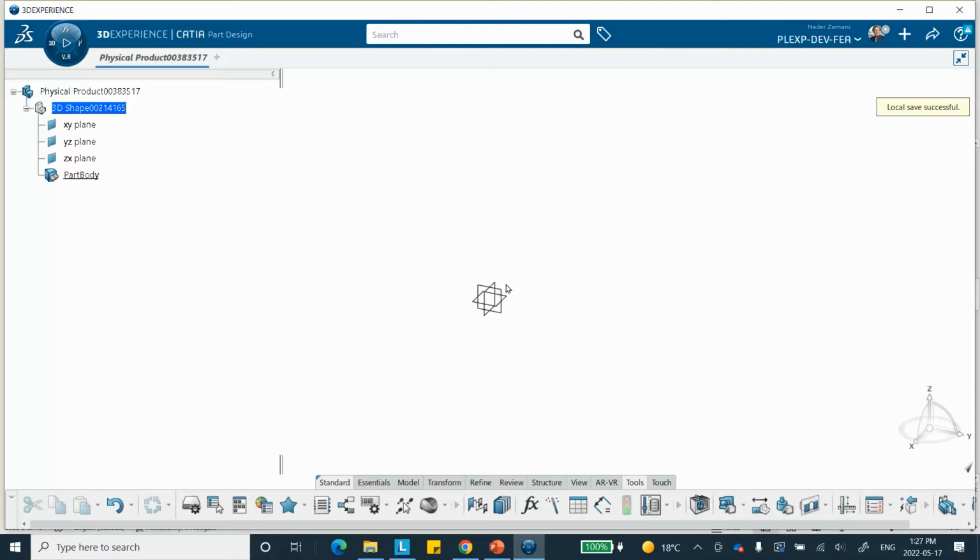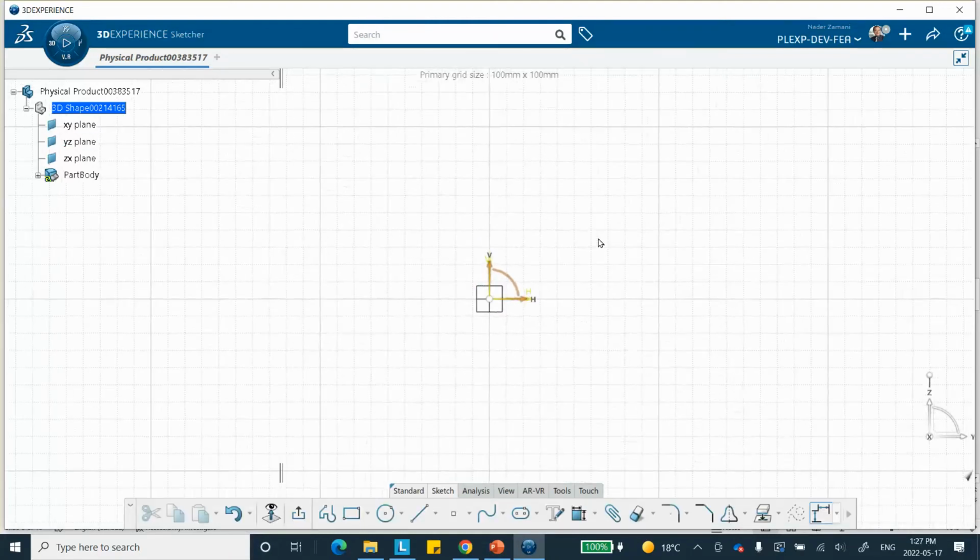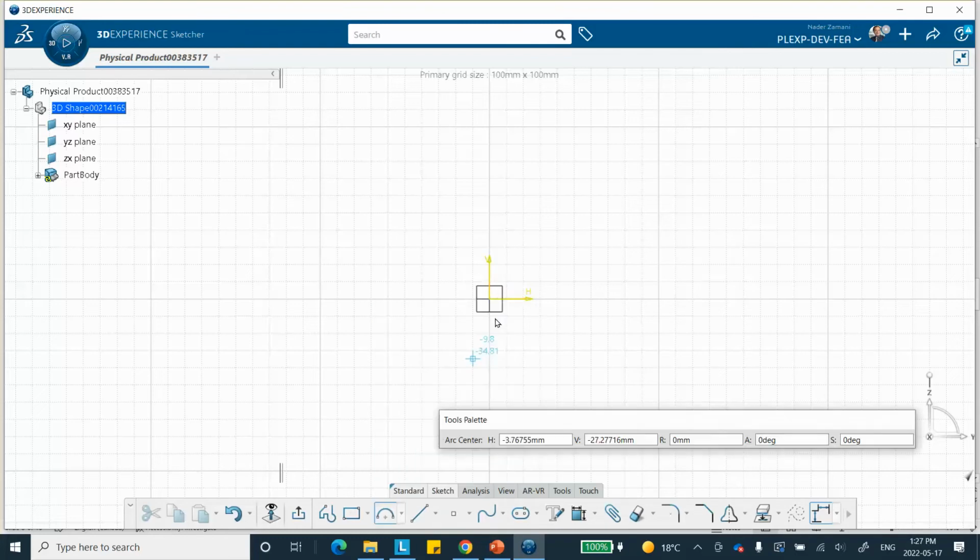So on a convenient plane, on that vertical plane, I will sketch. But we're going to be using a quarter of the model. When I say quarter, it's actually 1/8 of the spherical shell. So let me go ahead and make two 90-degree arcs, one like that.